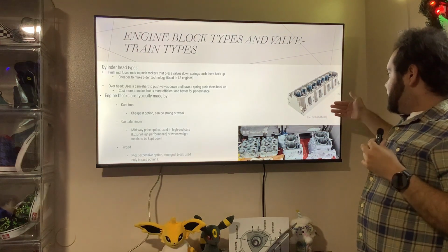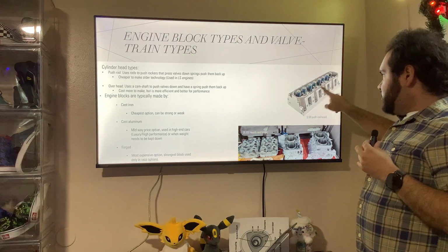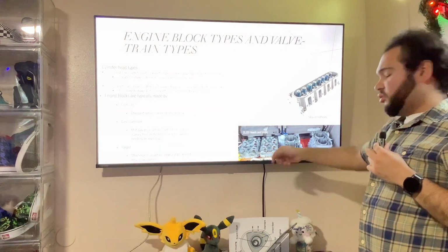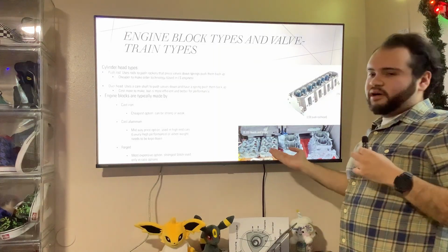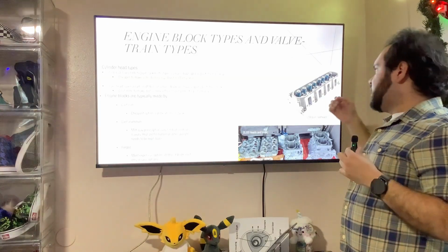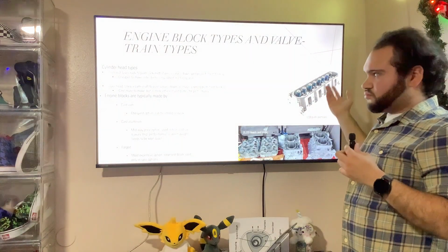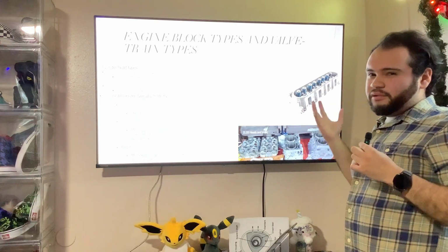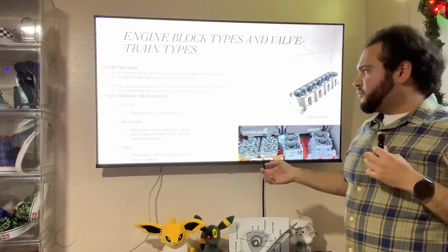As you see here, here's a push rod head out of the LS9. Very simple, while an overhead cam is more complex. We add more complexity with the overhead cam, but it can rev higher, it can be more fuel efficient, more manageable, while it's easier just to build a push rod head. But that's old technology, and only a few engines still use it, like the LS or LT engines from Chevy.